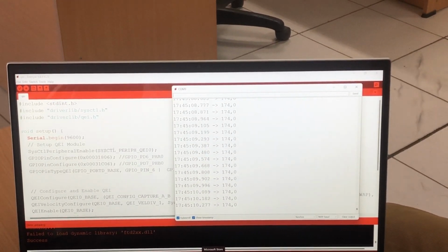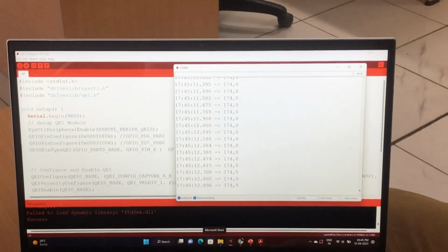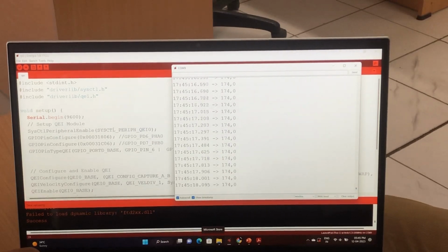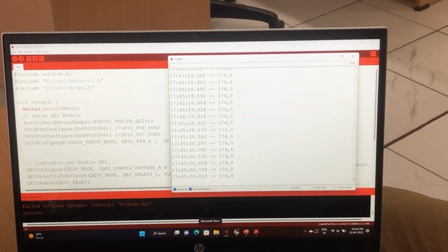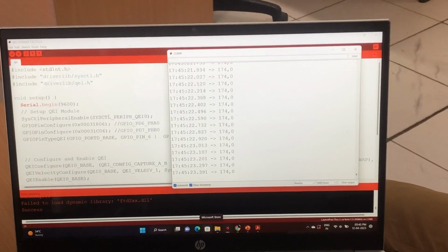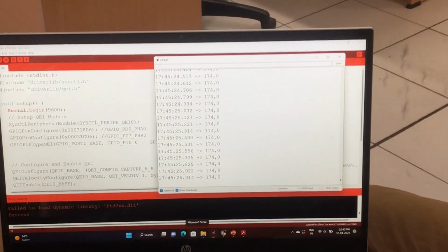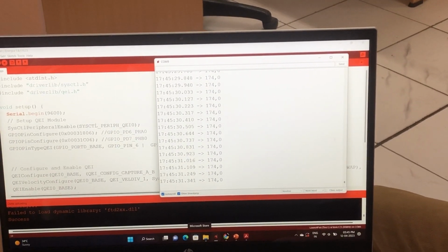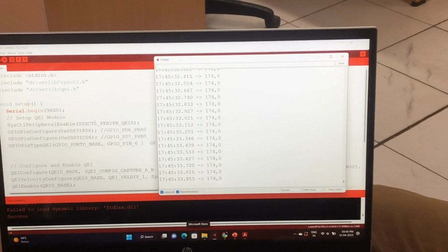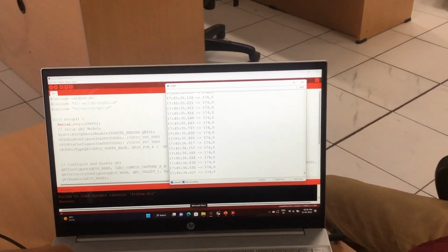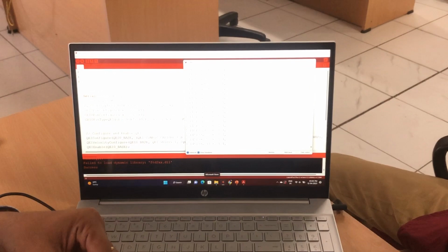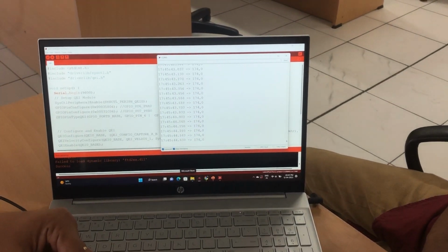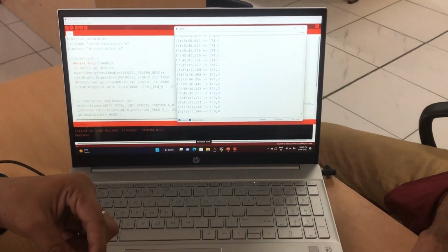All the odometer and speedometer readings are taken from the rotary encoder principle, which is called the wheel speed sensor in an automobile. With the help of the wheel speed sensor, we can measure the displacement as well as the speed of the vehicle. Based on these readings, the braking system works. ABS stands for anti-lock braking system and ESP stands for electronic stability program. The functioning of ABS, ESP and all speed-related, wheel-related or mobility-related activities in a car happens because of the wheel speed sensor.